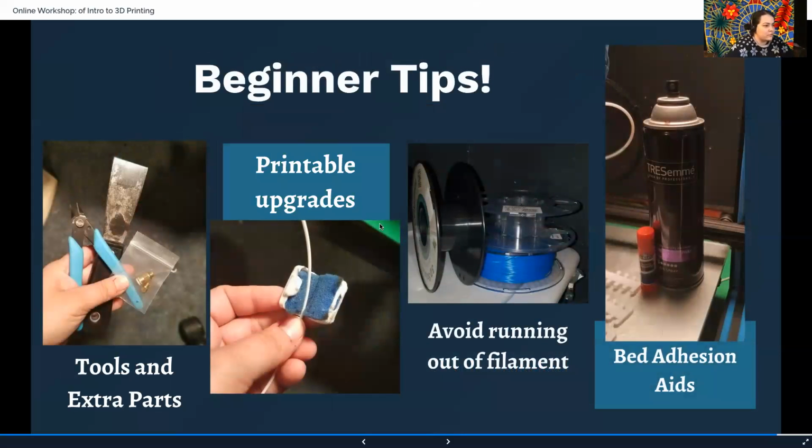And then also here are just a few tips and tricks that are common with 3D printers. Your printer will usually come with a set of tools like this. I recommend buying extra nozzles in case you have a failure and you don't want to wait for the part to come in. You just have them ready. They're pretty inexpensive. And then also the really cool thing about having a printer is being able to upgrade it with itself, like self replication. So once you get your printer, you can type your printer's name into Thingiverse or somewhere, and you can find all kinds of upgrades.